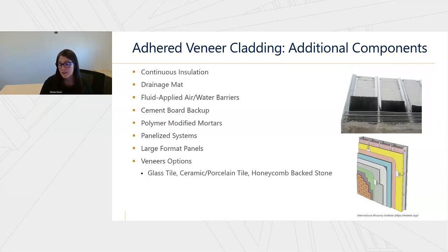This may be, for example, thin brick, where several thin brick pieces are included on a panel, and then that panel gets adhered to the system. Large format tiles, this is any tile that is over 360 square inches in size. And at that point, you move to an engineering design.